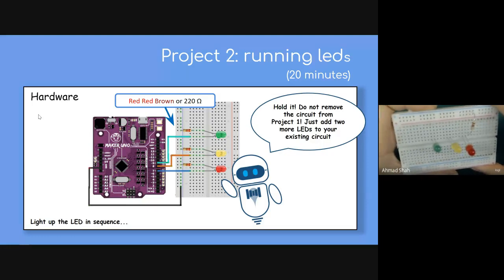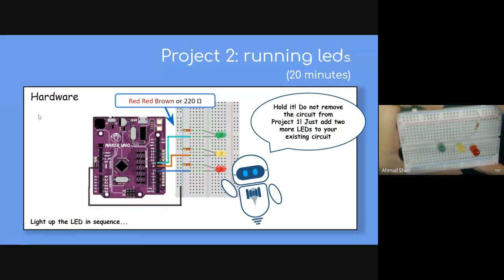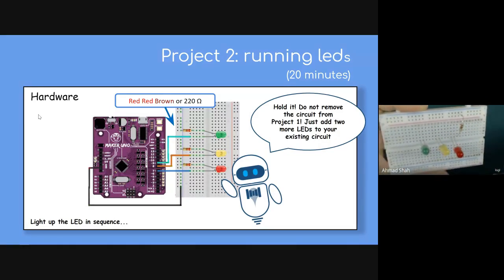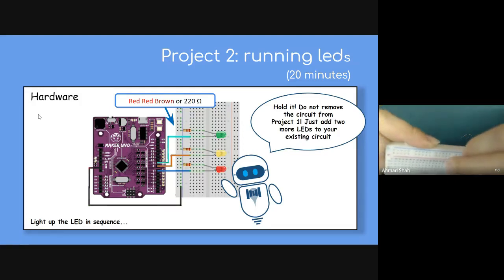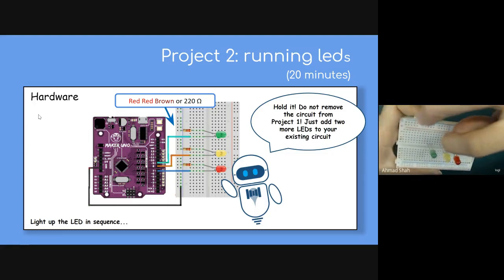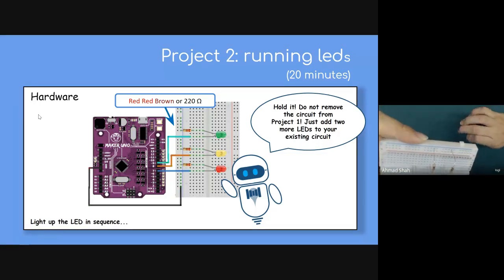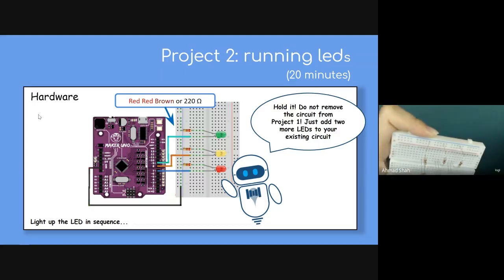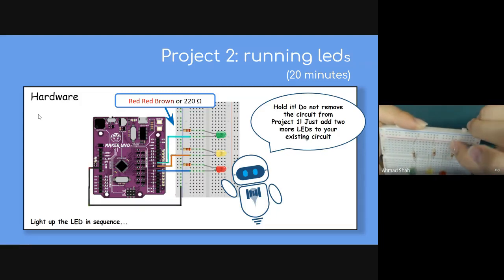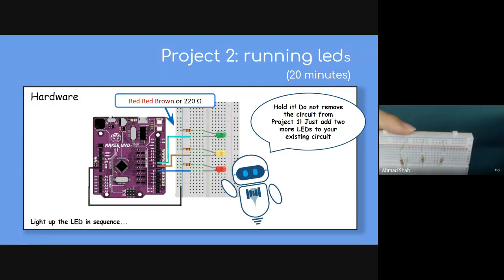Yeah. So same goes to the rest of the LED resistors. If you're able to do this, you can do the same for all the LEDs. So I will connect it at 16 and then negative. And then another one is 11 and negative. So in this way, when you're connecting in the same number with the negative leg, it means you're connecting the negatives together.